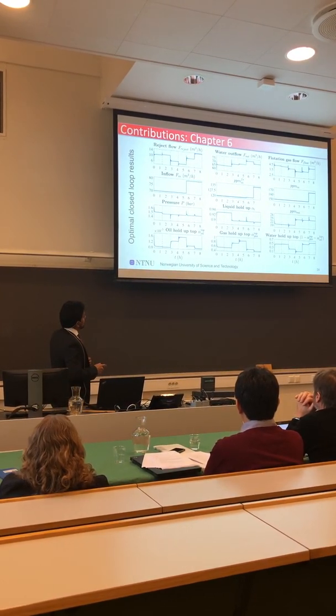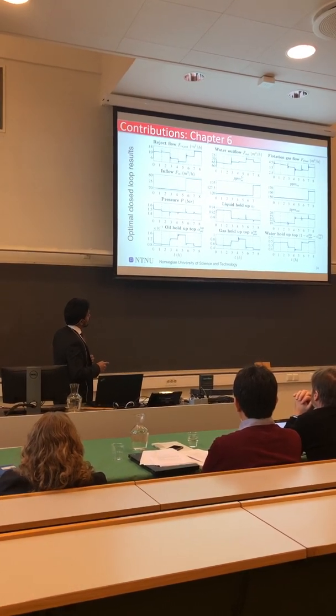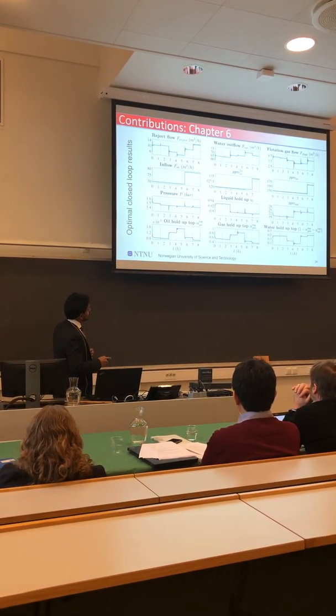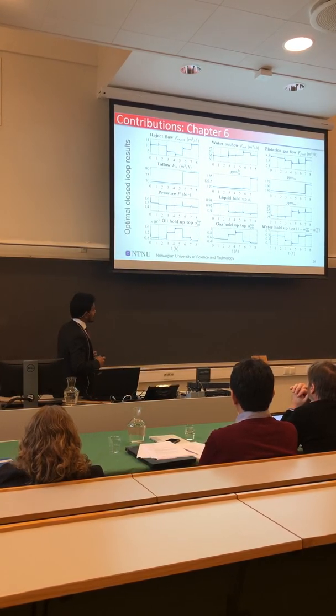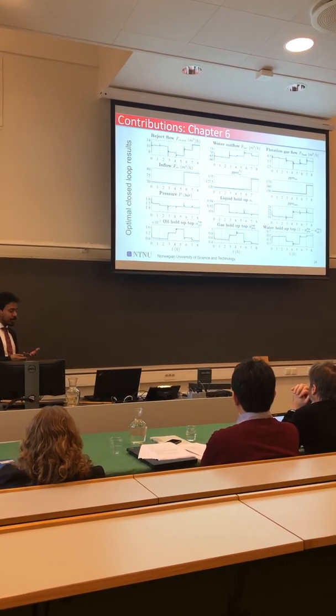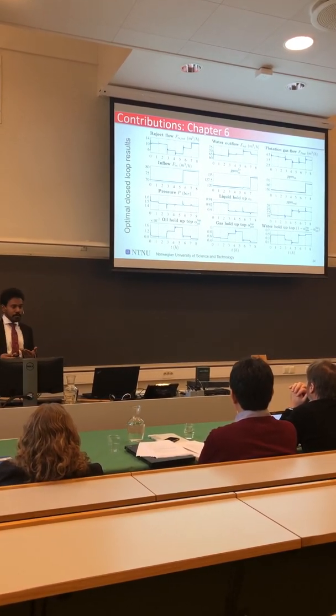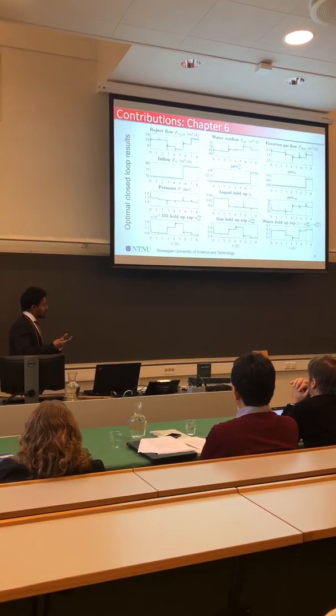At the same time, one important thing to note is that we start to see a gas holdup rise as we reach the most optimal point, which is between 4 and 5. We see the highest amount of gas holdup, and that clearly says that if we take more and more gas, only gas and oil out of the top, then we are not going to take. So this is apparently the optimal.